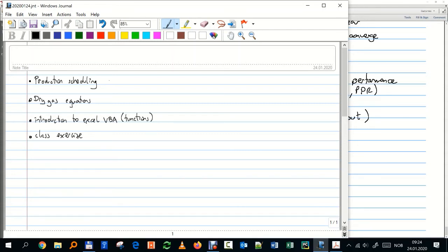But also due to bottlenecking, and all kinds of other things, design of the facilities, I want to compute the other two. If it's gas, then oil condensate, because it gives me this extra revenue that can change the economy of the field, and water because simply it causes a lot of issues in the plant. And also oil, the same thing. Oil, I want to calculate gas. Maybe gas I simply re-inject and don't get any revenue out of it, but it will cause some changes in the design of my separator, my compressor station. And water, the same thing.